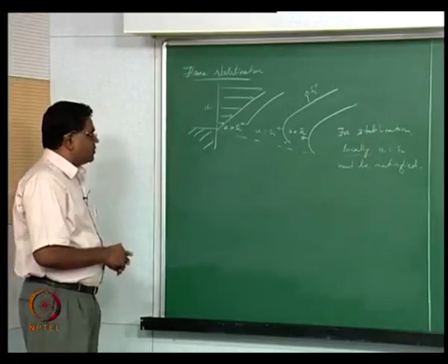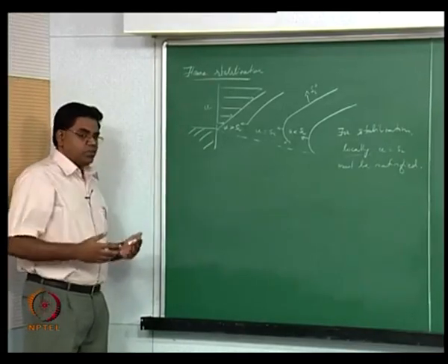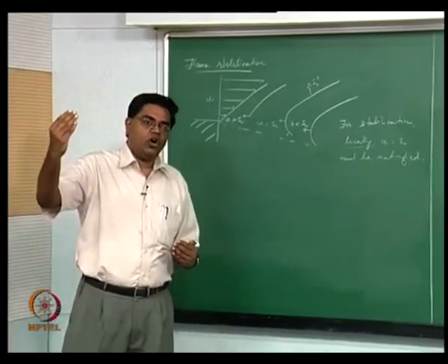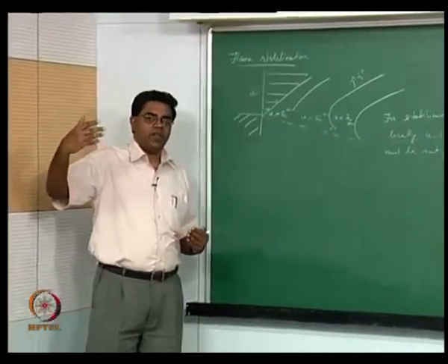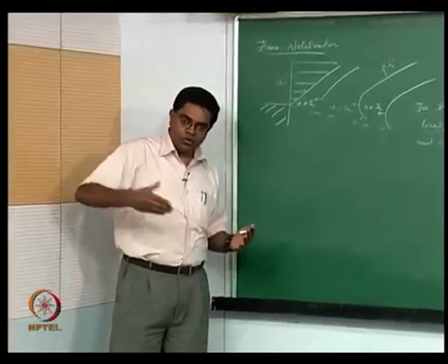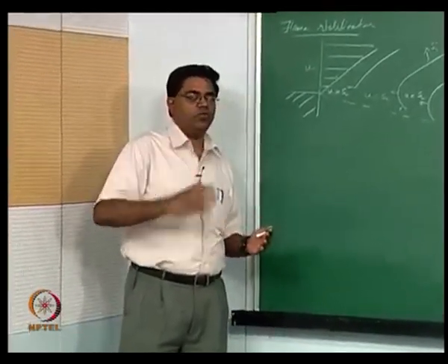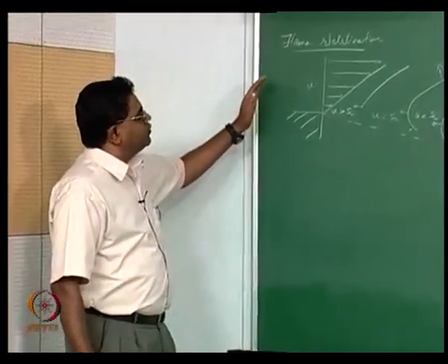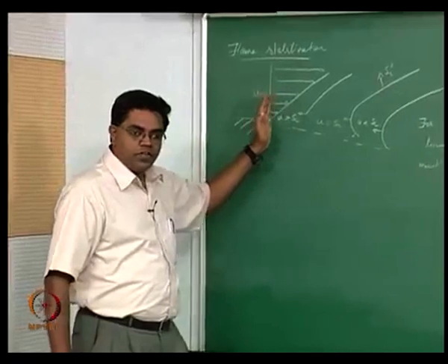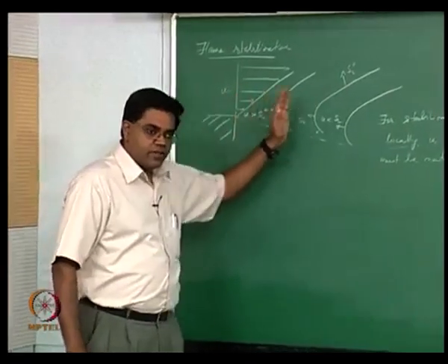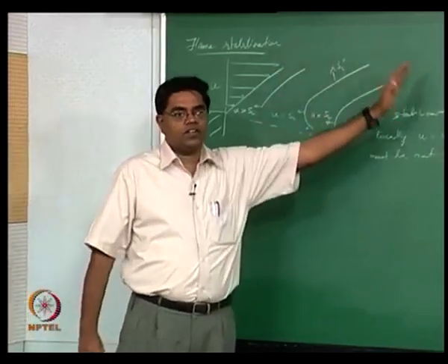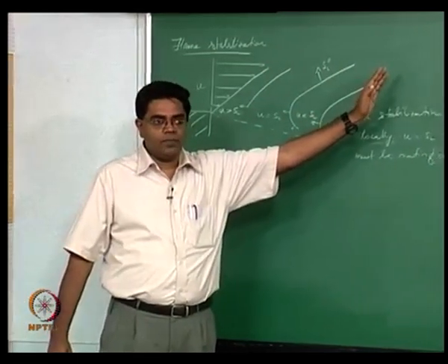The second situation is where we do the opposite: we progressively increase the velocity relative to the flame speed, or progressively decrease the flame speed by going to leaner and leaner mixtures for the same flow velocity. That gives the flame a tendency to get established further and further out, and at some point it cannot be stabilized anymore and it starts blowing off, right.